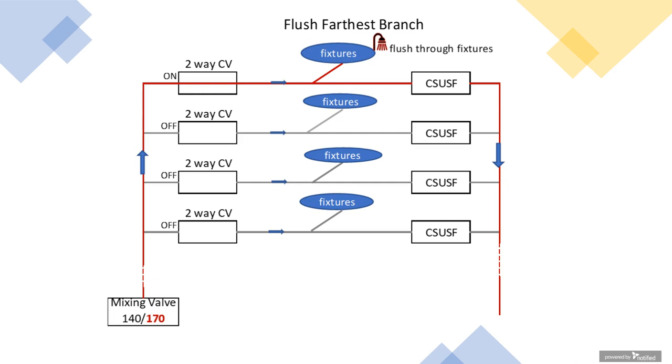So now you have a scenario where all the valves are off, nothing's flowing through the system, the water got changed to 170°F, and all the fixtures are open, and whatever personnel are there to manage the process are there observing the fixtures to make sure there's nobody around there that would get hurt or scalded by the hot water.